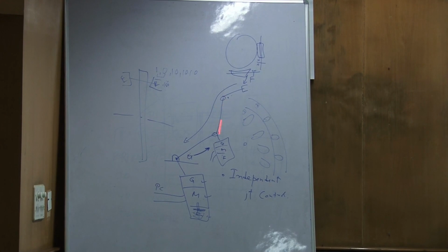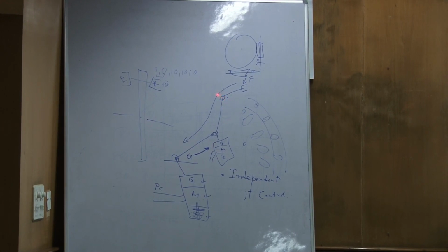So one of the experiments is you have a point there, and I want to go. Suppose I'm here and I want to go to some other point. Then doing inverse kinematics, I can find the corresponding angle, and then I can see the equivalent PWM for that angle, and then give it there, and it will exactly go and stop there. Okay. So I can actually do motor control very easily without getting into PID controller design and all that, simply by controlling the microcontroller through a servo motor.